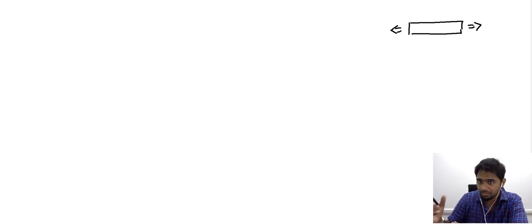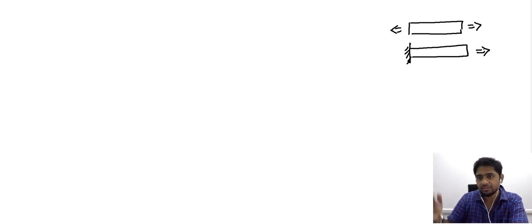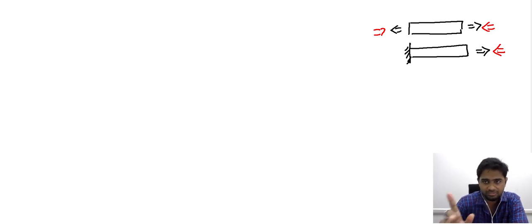Now the same load can also be imposed by fixing one longitudinal end of the sample, and applying the load on the other loose end. In the same manner, we can impose the compressive load just by reversing the direction. So what we need not do is change the way we position the sample. This is a significant similarity between tensile and compressive loading. That is, the way we handle the sample does not really change much, but the direction of load gets reversed.